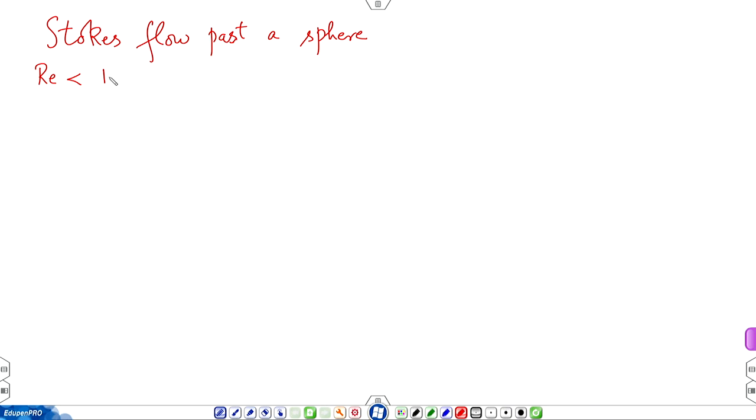So we are talking about Navier-Stokes and the difficulty in solving the Navier-Stokes equations. We look at limiting cases and see if some solutions can be built up. One limiting case, well, actually we have already seen, is fully developed flow, where the inertia terms are identically 0. Then we looked at the limiting case where the Reynolds number is small, for which the viscous terms are dominant relative to the inertia.